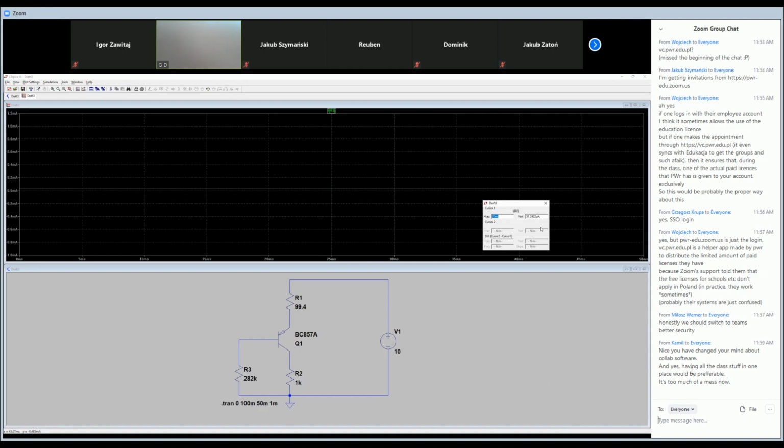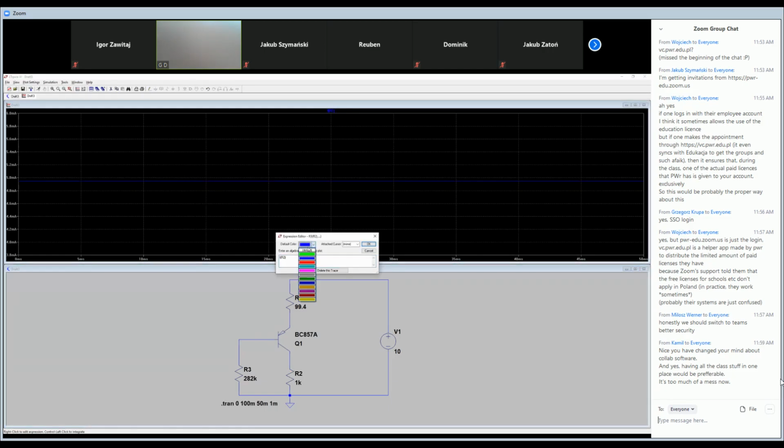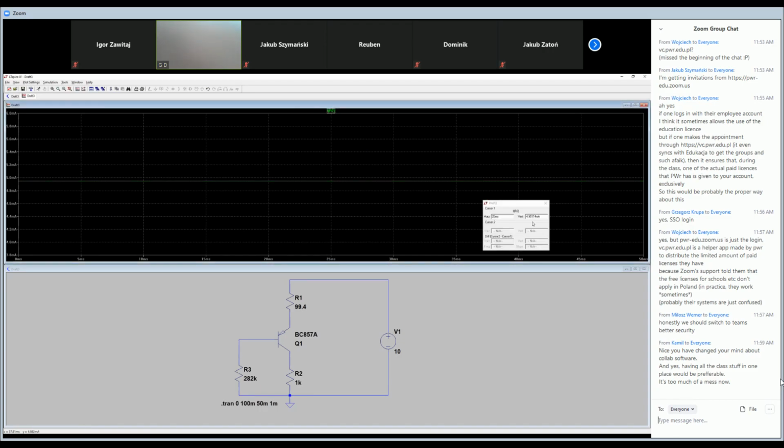31.24. Yeah. So as you see, it is almost that was calculated. Great. Okay. What about the IC current? It is here. I will change the color. How many is it? We chose that IC current should be 5 milliamps. In simulation, as you see, it is almost 5. It is around 4.95 milliamps. Great.